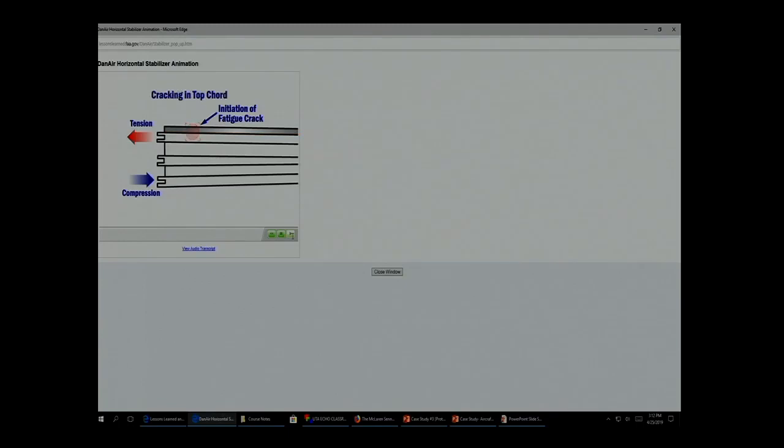The upper cord crack grew in fatigue over a period of 7,200 flight cycles through the upper cord. However, once the upper cord was fully fractured, the assumed redistribution of the loading to the center fail-safe cord did not occur. Because the crack location occurred outboard of the lug, the 11 inches of intact upper cord structure provided an unanticipated load path.